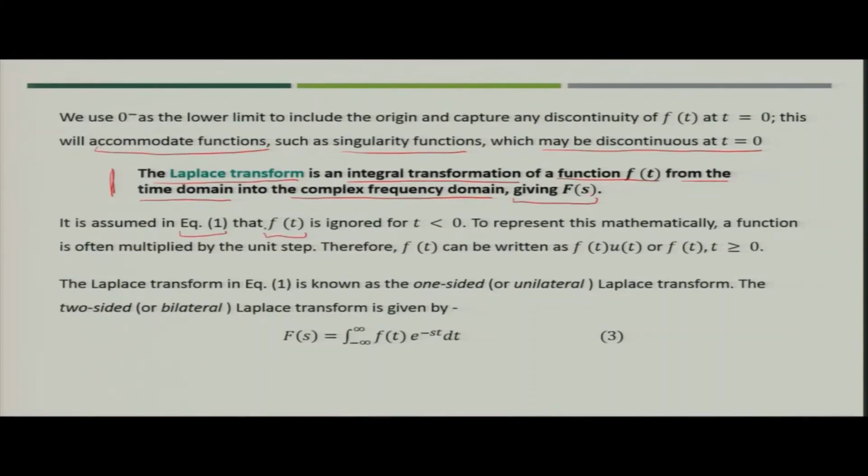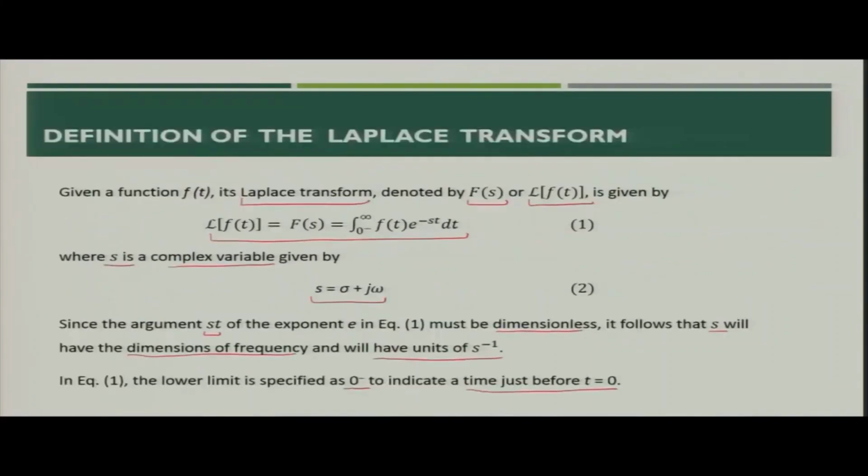Now, if you assume that in equation 1 f(t) is ignored for time t less than 0, you are representing this mathematically as the function multiplied by the unit step function. So, you can simply write f(t)u(t), or f(t) for time t greater than or equal to 0.